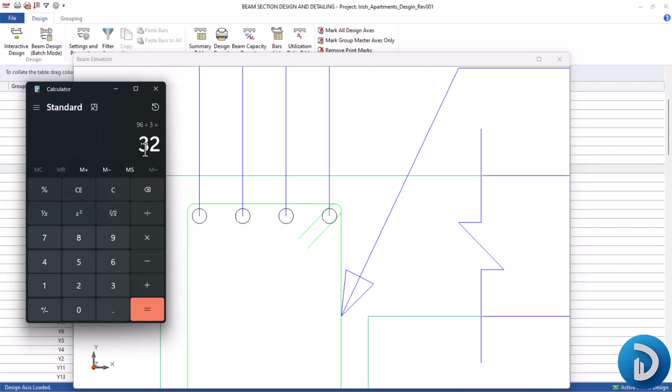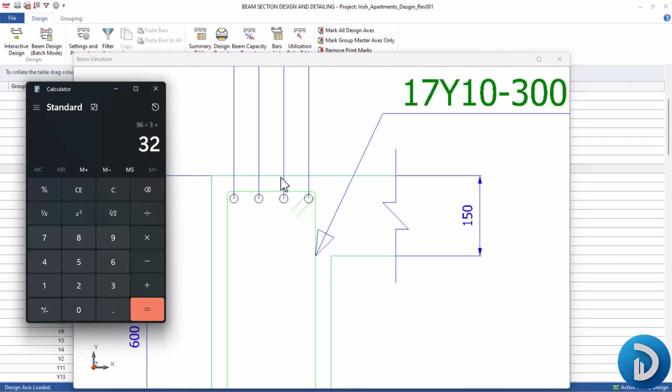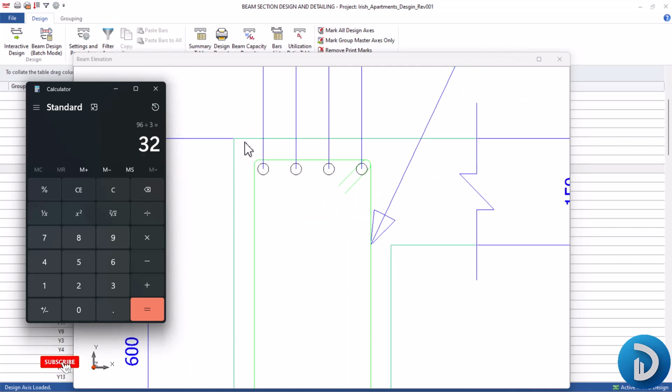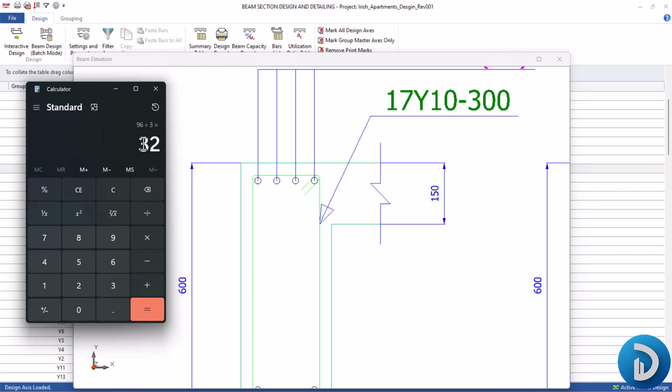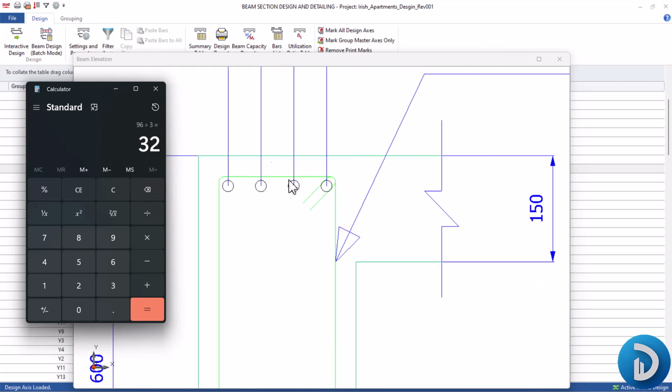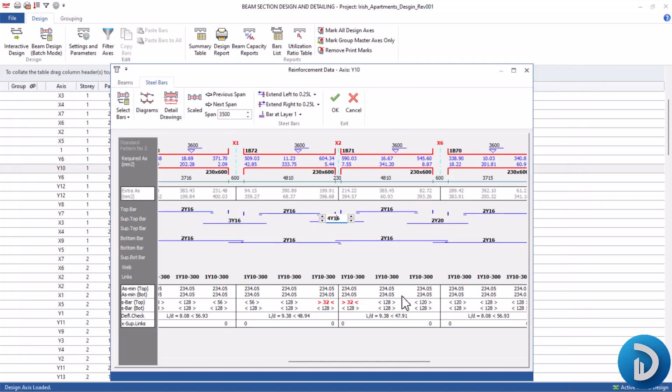But it is advisable to keep your coarse aggregate size at 20 millimeter, because do not forget that you also have to pass your concrete up to the part where we have our concrete cover. Okay, so this is actually satisfactory because 32 millimeter is way above 20 millimeter. So we can choose to ignore this part in red because we have 32 here, and it will actually accept our coarse aggregate.